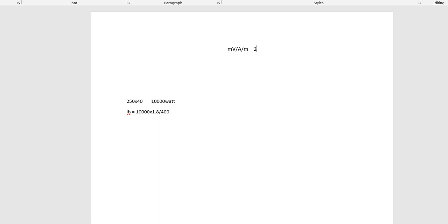You know we have 2.8. Now multiply 2.8 by your 45 amps you are working with. Then multiply again by 500 meters. Then divide the result by 1000. All right, pay attention now. Remember that 2.8 factor was the one we got from the table.